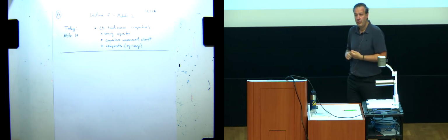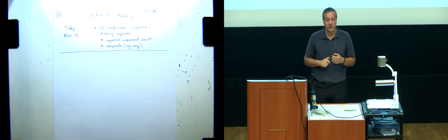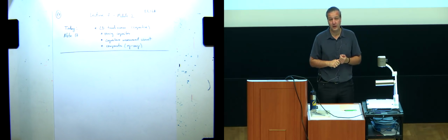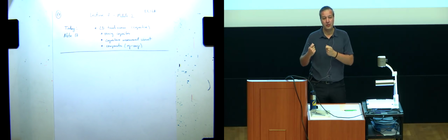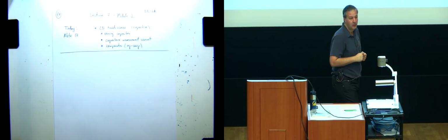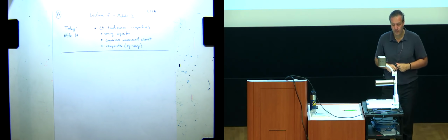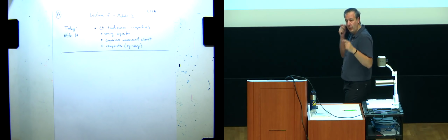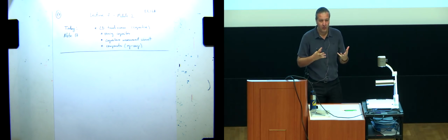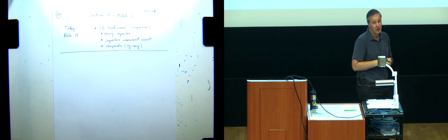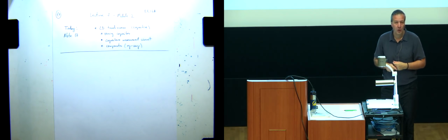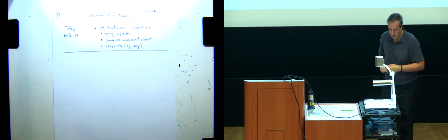Then look back into circuits with capacitors that we did so far to figure out how we can actually measure the value of that capacitor, because that will be our unknown. Right? When we put the finger over a pixel, there will be some capacitance that changes, so we want to figure out what that is.